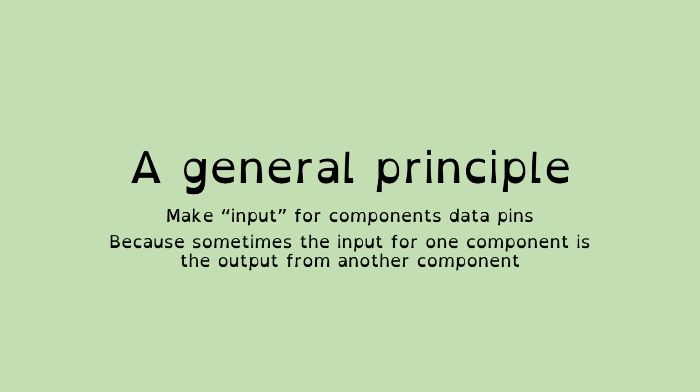The answer is because sometimes the input for one component is the output from another component, and you want the two components to connect together. And that means that that output is already a register. So rather than multiplying up the number of registers by having an input and an output register in each component, I'm going to have this principle that if there's a component that has a register built into it, then that register is conceptually the output.